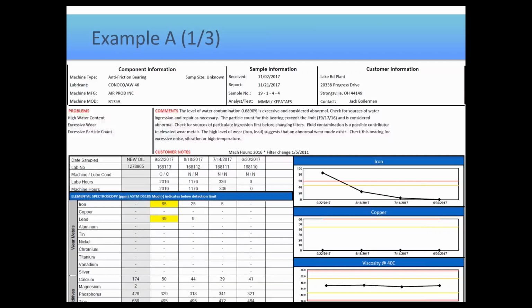Suppose we simply resample the machine to see if we fixed it. The better question would be, when do you resample it? And the answer is, you do not resample it today, and you certainly don't resample it tomorrow. What you do is you wait for the normally scheduled interval to come back. Because if you sample it too soon after doing something, you're not likely to see much change. But then the next question is, if you wait that normal interval and you sample it under normal conditions, everything's just the way it's always been, what do you expect the next result to look like?